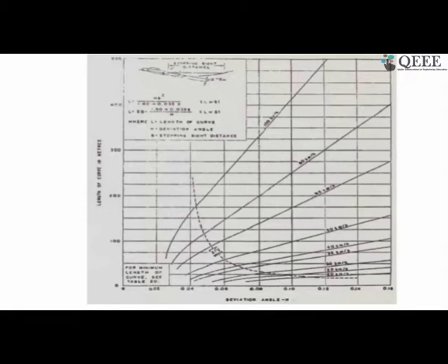The next question was, what will be the effect on the road if the design consideration of the summit curve is not suitable? If it is not suitable, it means the speed is not considered properly. As I told you, if someone is traveling at a higher speed, the vehicle can be thrown off the summit curve. That is the major thing which is going to happen. The other thing is that if it is not designed properly, particularly if it is not meeting the stopping sight distance, and there is a stationary object lying on the other side, the vehicle may not be able to see it and get into an accident.